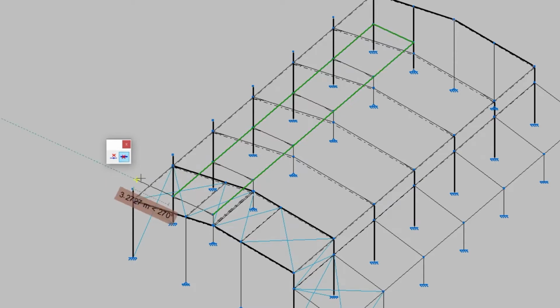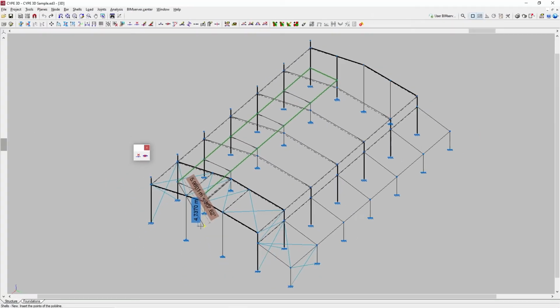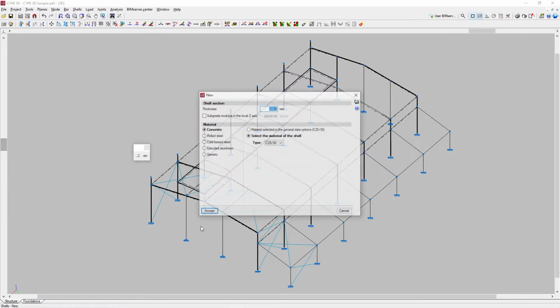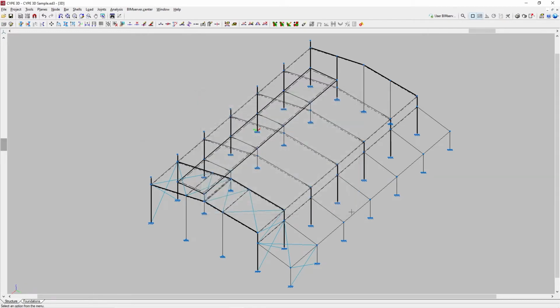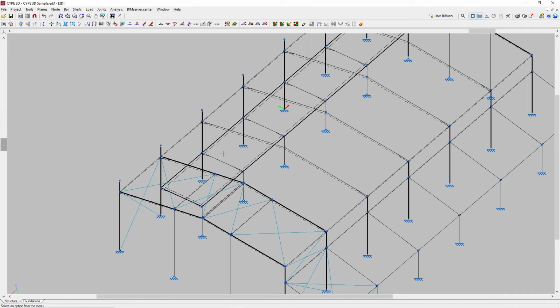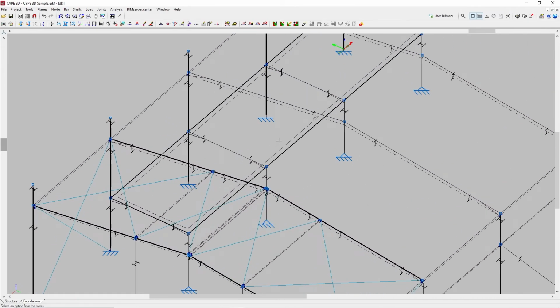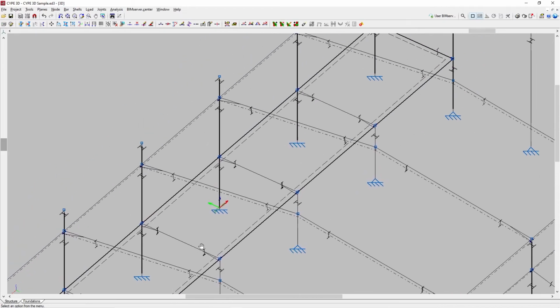After selecting all the points on the perimeter of the shell, we click on the right mouse button to finish the process. From this point on, we can continue drawing other shells on the model, or we right-click the mouse to return to the definition panel. If we click on Cancel or close this panel, we exit the option. The shell will be connected to the rest of the elements of the structure if they are in contact with its edges or with the nodes or bars contained in its geometry.